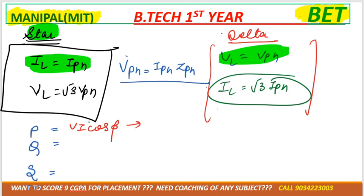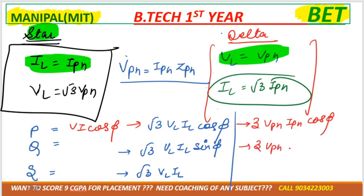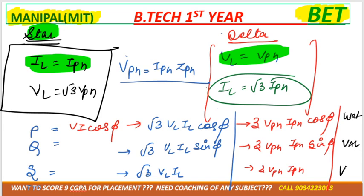If we want to calculate power in terms of line, active power would be √3 VL IL cos phi. Reactive power would be √3 VL IL sin phi, and apparent power would be √3 VL IL. In terms of phase, it is 3 VPH IPH cos phi, 3 VPH IPH sin phi, or 3 VPH IPH. The units are watts, VAR (volt ampere reactive) and VA. You need to learn these formulas. If you calculate by line or phase, the answer would be the same in both cases.